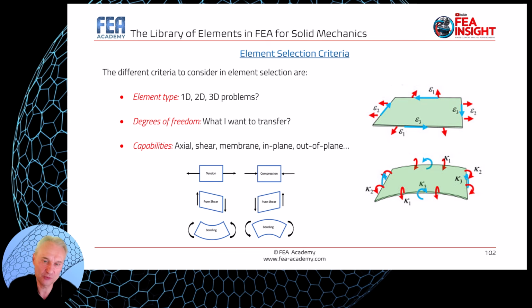So the material property that you want to simulate will influence your selection of elements. Finally, not all elements are compatible with nonlinear solutions. So when planning to run a nonlinear solution, certain elements should be prioritized and used first.